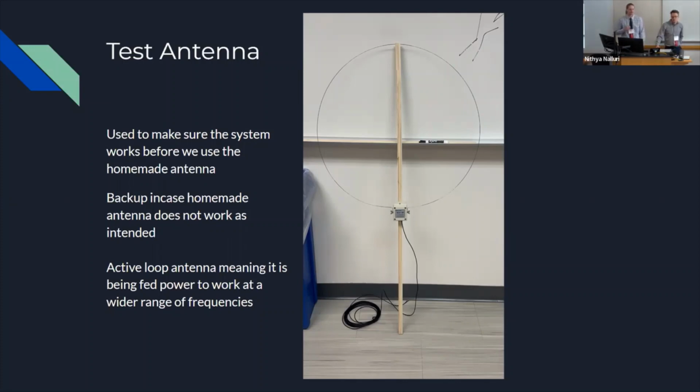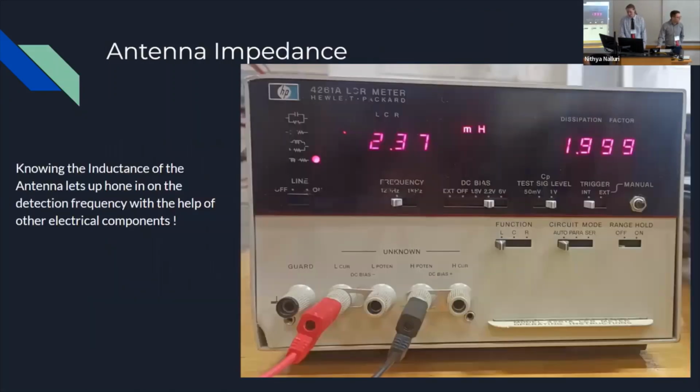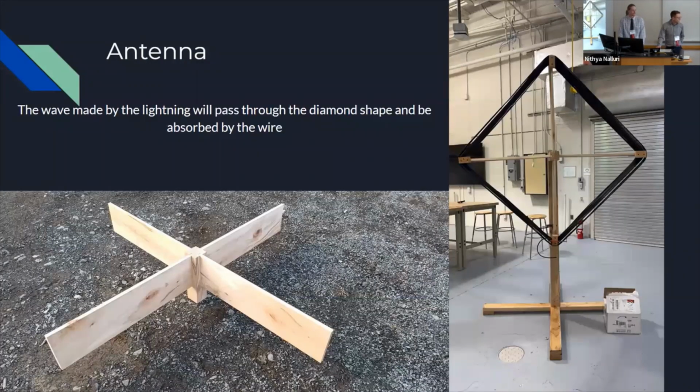I found the fiber optic ones were reliable anyway. I played with those things a while back. You did excellent work, especially on the antenna that you passed. I would love the engineering in the antenna because you chose 300 kilohertz, you're away from the broadcast band, where you don't have false positives. The fact that you're way down at 300 kilohertz and you're getting that coverage, you're fine. That should work.